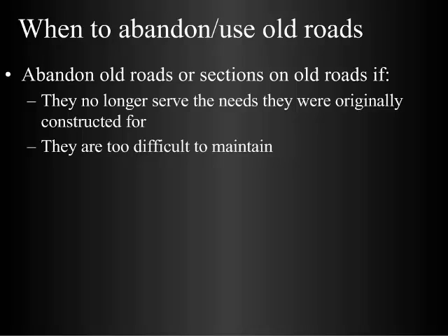You may end up using segments of it. You may be using none of it. The other thing is if they're too difficult to maintain. They may be built in a stream bottom that's constantly eroding. It may be built on a steep slope where the road's always filling in. Those are things to take into account when determining if you're going to continue to use a road.